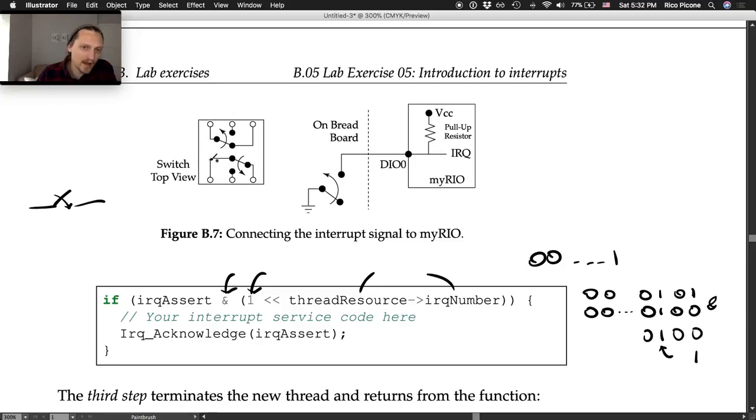And the switches that we have actually have 6 terminals, which is pretty common to see. And with 6 terminals, the other side is just a mirror image of it. So actually not a mirror image, it's a reverse image of it, a rotation. And the rotation gives you another, so it throws both switches when you push the button, so they're not totally independent of each other. But you can control multiple circuits with just one switch if you want.